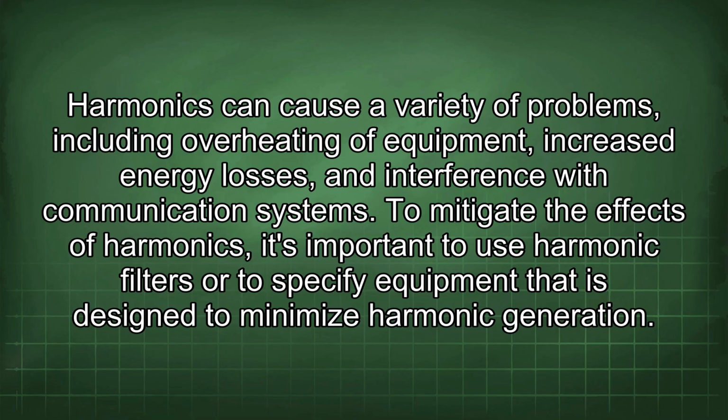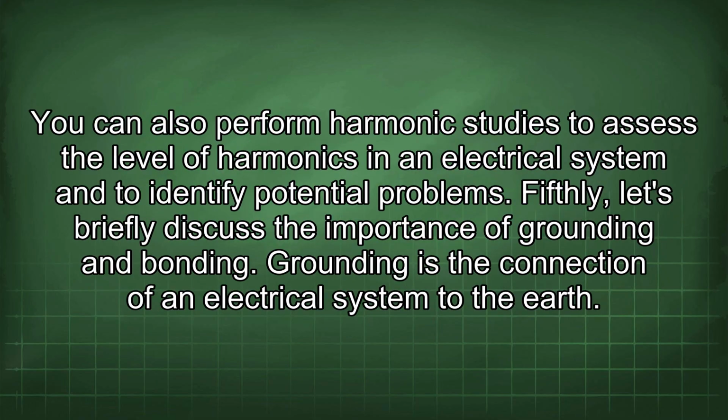To mitigate the effects of harmonics, it's important to use harmonic filters or to specify equipment that is designed to minimize harmonic generation. You can also perform harmonic studies to assess the level of harmonics in an electrical system and to identify potential problems. Fifthly, let's briefly discuss the importance of grounding and bonding.